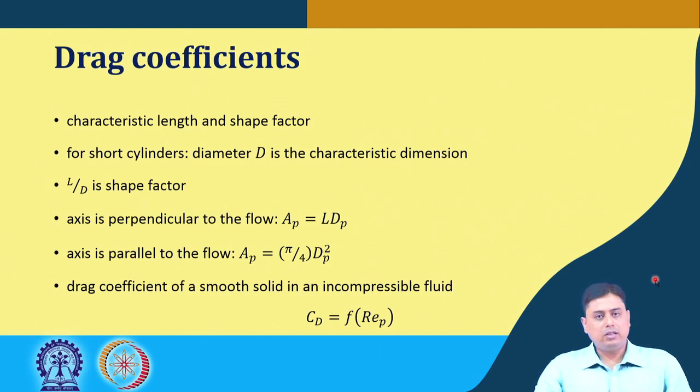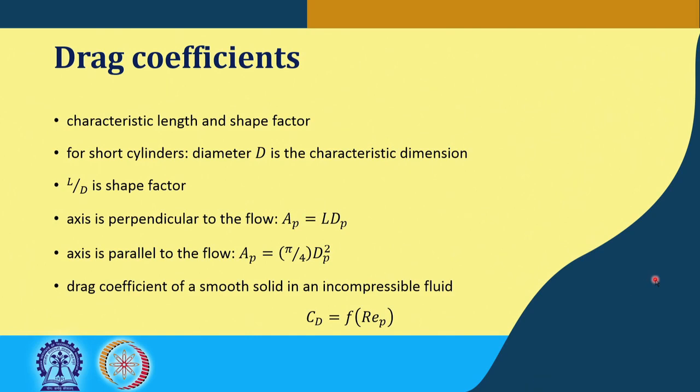So that is why for the irregular shaped particle we need to define the characteristic length and its shape factor. So how are these determined? Let us understand such a scenario with an example. As I said, which one is the dominating length or dominating dimension, you can understand while considering the object and that particular flow scenario.